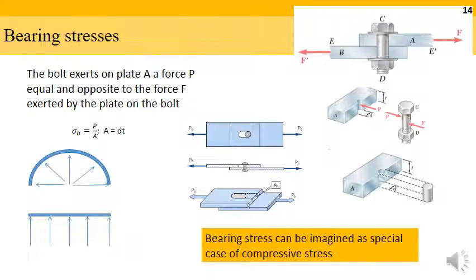This is bearing stress. To understand bearing stress better, you can do a small experiment in your house. Take a paper, punch a hole inside it somewhere, put your pencil through the hole, and hold the paper from both ends and try to pull the pencil away from the hole. You will see that you are applying the load on the pencil, but the paper is getting subjected to compressive stress and is tearing apart in the region which is very close to the hole. This is known as bearing stress. Bearing stress can be imagined as a special case of compressive stress.